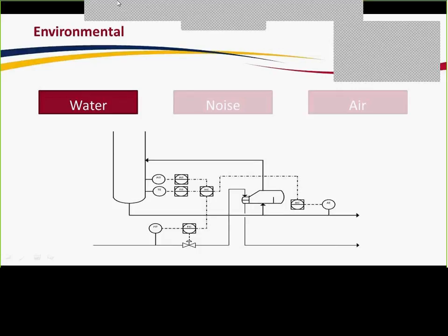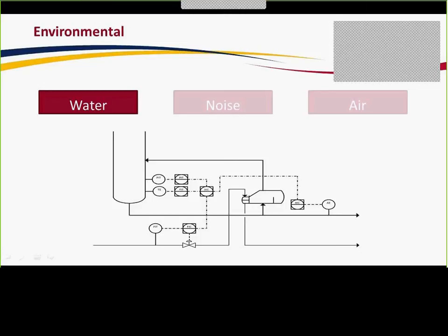So shown in this picture above is the bottom of the water column. This distills the water from the methanol and the DME. And the way we are controlling the composition and temperature of the water is through a control system. So we have a concentration analyzer, which is measuring the concentration of methanol and DME in the water stream leaving the column.